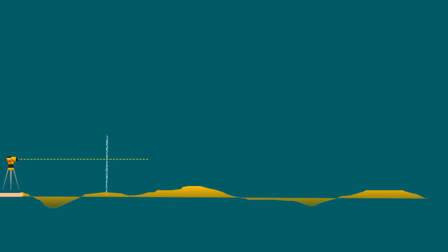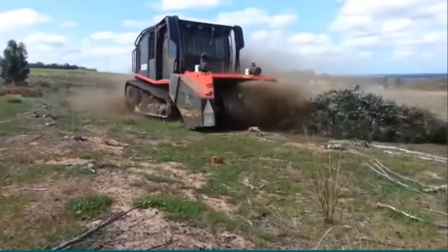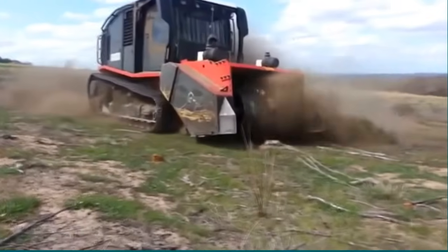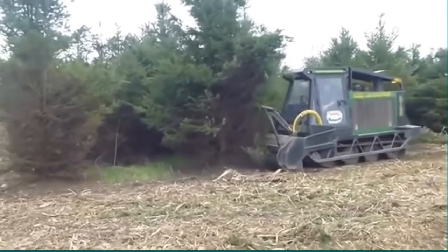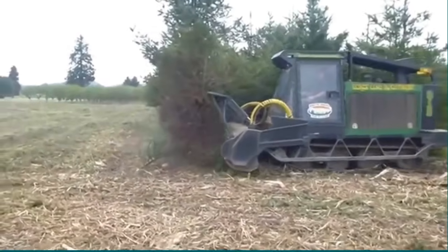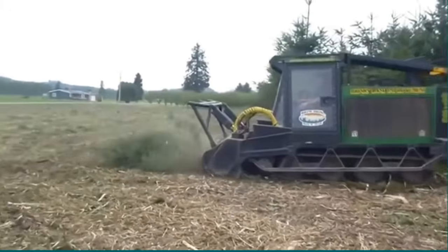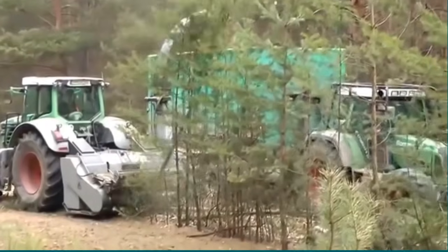Before starting of any work, the reduced levels of natural surface shall be taken for record, which will support to calculate the quantity of excavations done during the cleaning process. Usually, a subgrade will need some basic preparation to make it fit for construction purposes, and this process is known as subgrade formation or reducing to level. It is bad practice to construct a pavement over surface vegetation or topsoil as organic material. It will decompose, which could lead to the formation of voids in the covering layers, which could lead to settlement of pavements. The simplest form of subgrade formation is site strip.